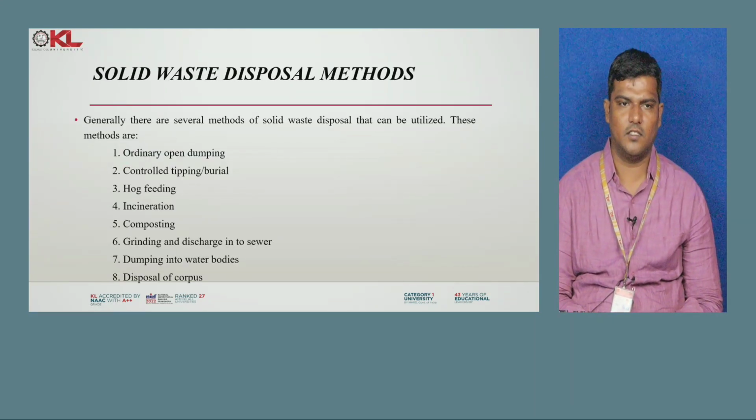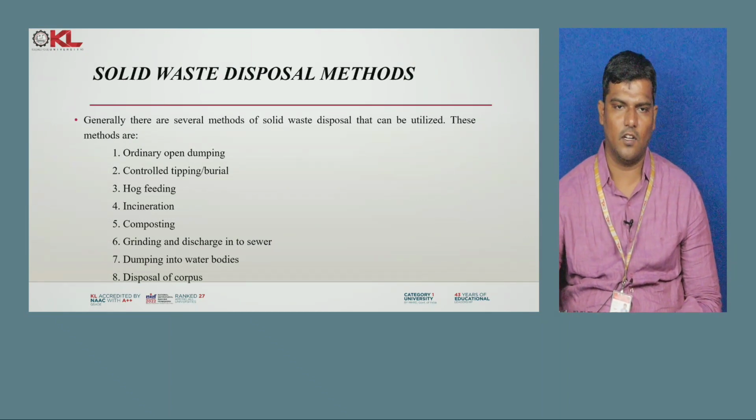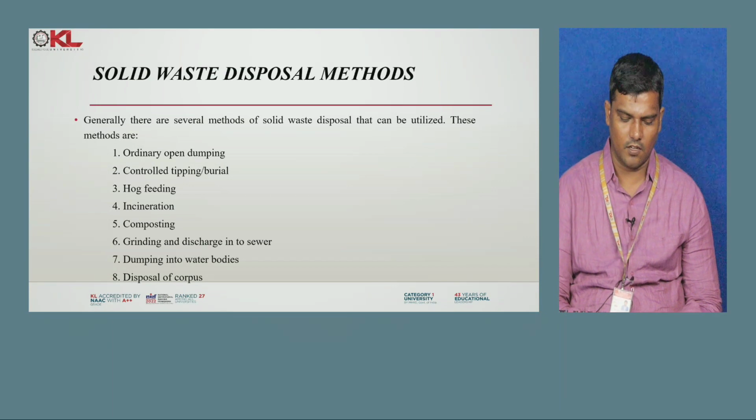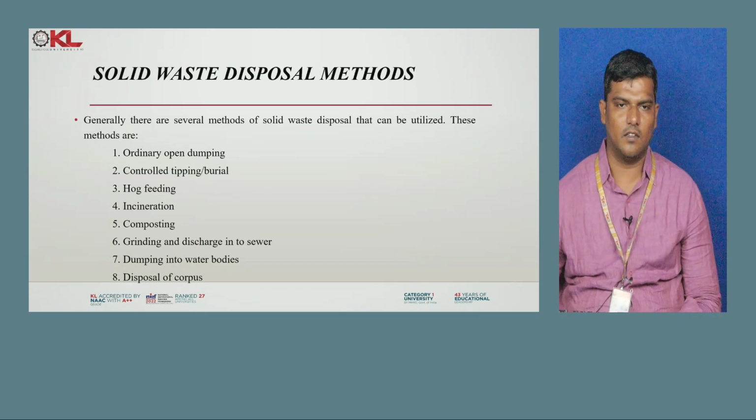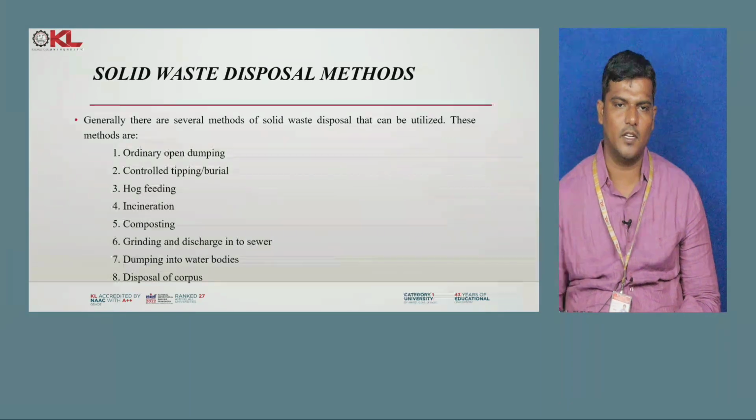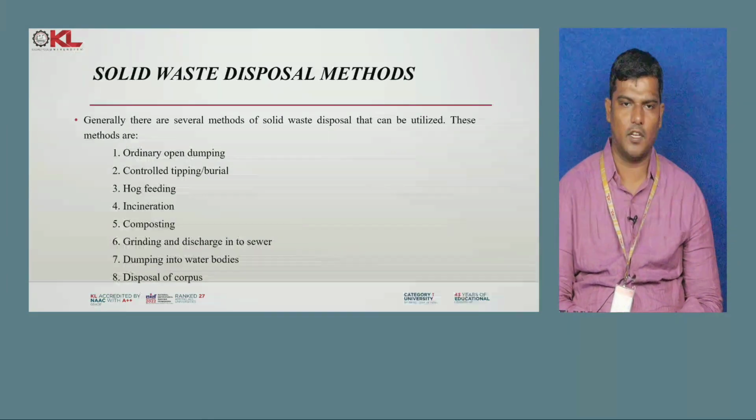Coming to the general methods that can be utilized for solid waste disposal, the first one is ordinary open dumping, which nowadays people are not using. Previously, as the population was less, people generally used ordinary open dumping over a course of time. If the waste is dumped at a designated location, automatically some amount of smell will be generated, and flies and debris will be carried into the air, which damages the environment. So nowadays ordinary open dumping is not preferable.